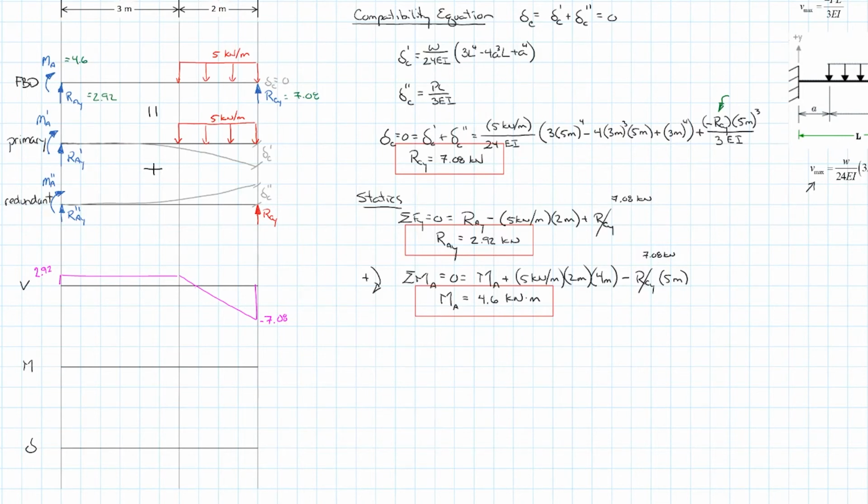Okay, and for the step to get from a shear force to bending moment diagram, it'd be helpful to just note a few things in here. So I'm going to note some of the areas. So the area here is equal to 8.76. Area in here, 0.8526, and I'm just using similar triangles to figure out what that distance is in here.